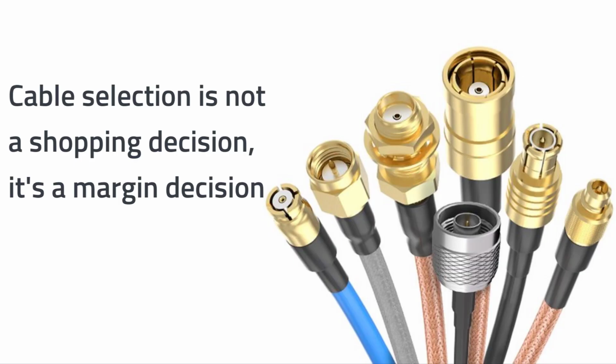Loss increases with frequency. That's not optional. It's driven by conductor loss and dielectric loss. At higher frequency, skin effect concentrates current near the conductor surface, increasing effective resistance and heating. So two cables that feel equivalent mechanically could behave very differently electrically.